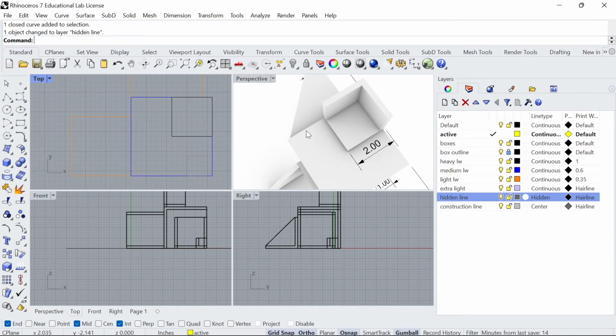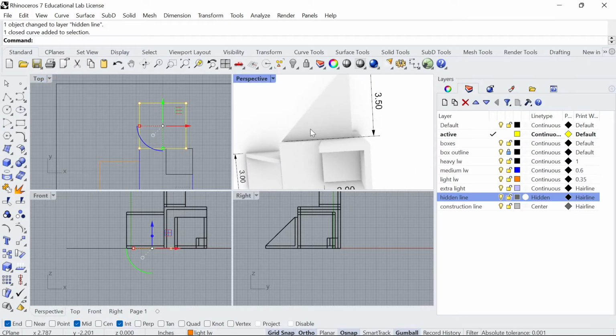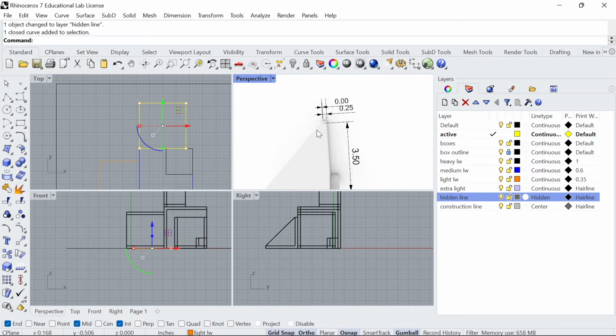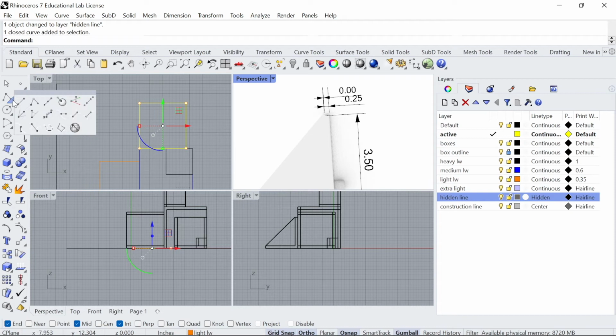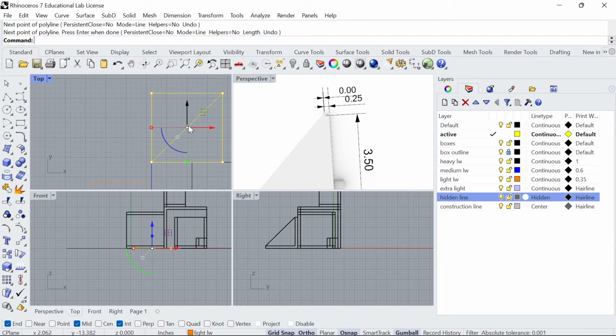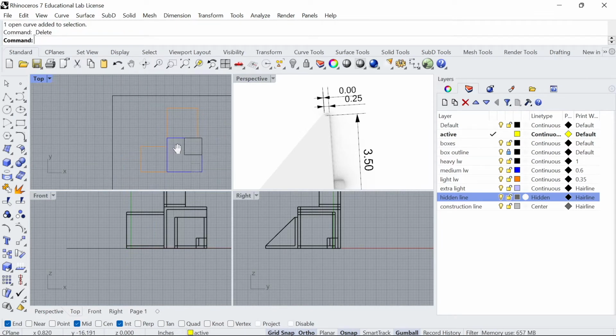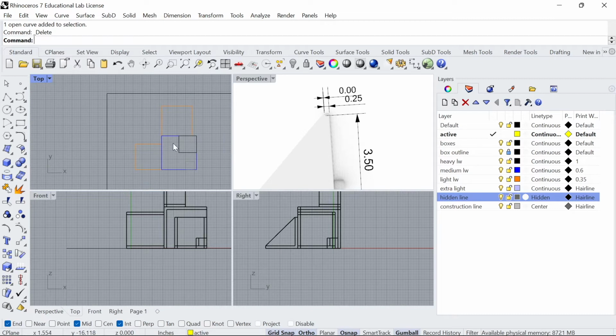The next thing we want to set up is the thicknesses of the walls. Obviously, I haven't covered that at all yet. Also, this box right here hasn't been cut. I want to represent its cut after I draw the thicknesses, because you can see in 3D, you have this 1/4 inch where it starts to be chamfered off. So I don't want to just draw a diagonal line right here. That wouldn't make any sense, because I'm not taking into consideration the 1/4 inch cut. Now, in your case, your object might look slightly different. I have no idea, but in my case, I want to be aware of that.